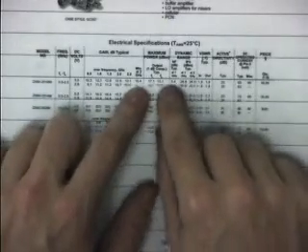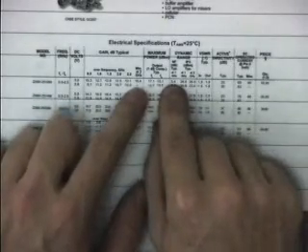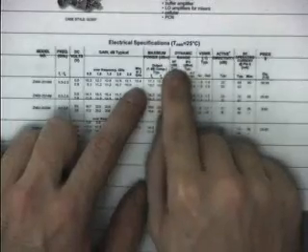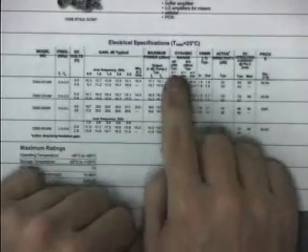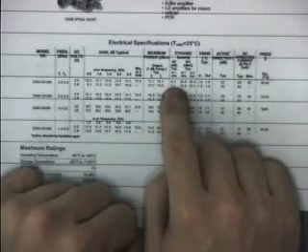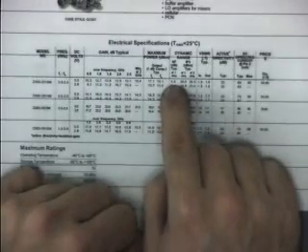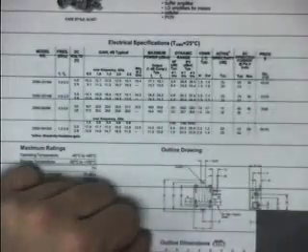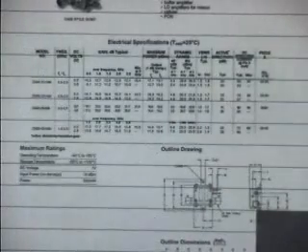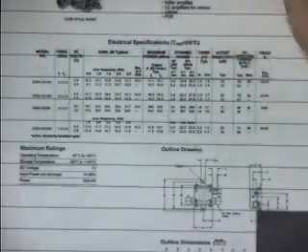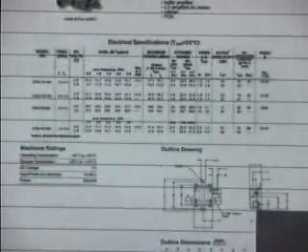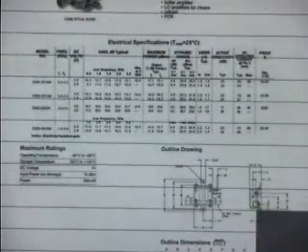You'll notice in this column, here's noise figure, measured in dB. So they've taken 10 log base 10 of the quantity we've put on the board. It's measured at 1 gigahertz, in the center of its bandwidth of operation. I see a value of 5.4. So that's going to almost quadruple the amount of noise if you have about 290 Kelvin going into this amplifier. 290 Kelvin in, about 1100 going out in terms of Kelvin.